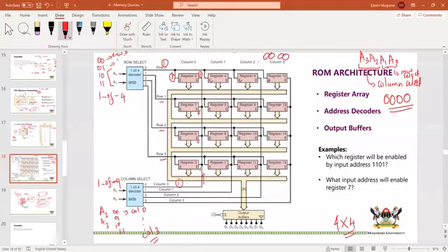This is a data bus. And we are reading, so the information in this register goes on the data bus, but there is no other register that has information on that data bus because all of them are not selected except register 0, and that information will flow along the bus and come down here. You can see this number 8, it is telling you that the size of the word is 8, so this is an 8-bit data bus.